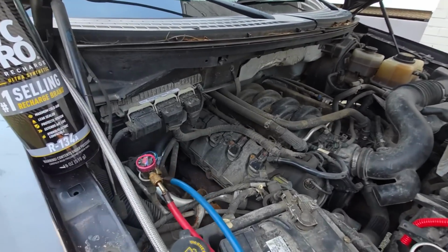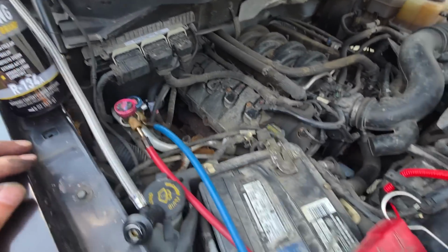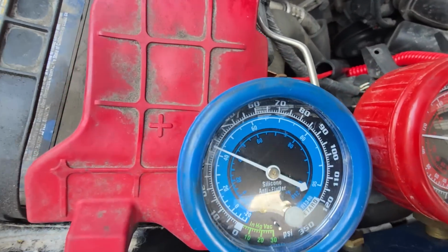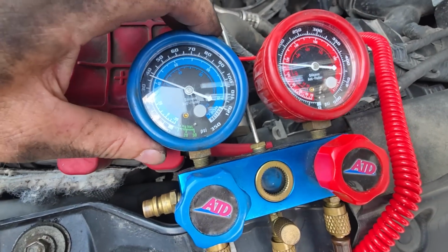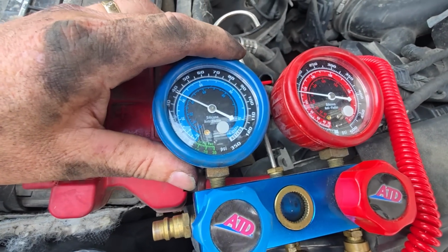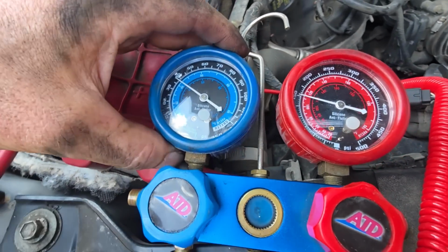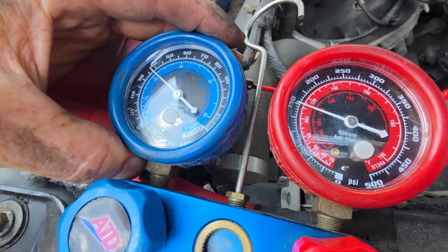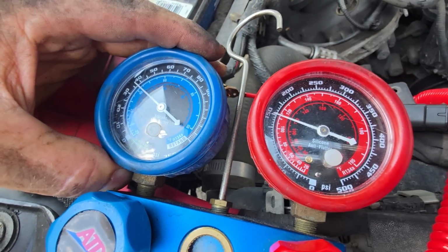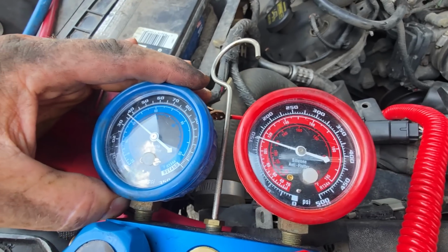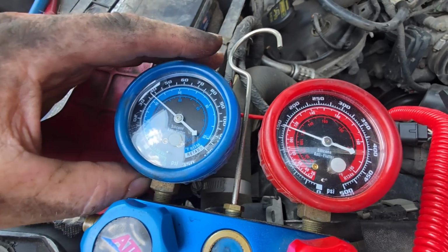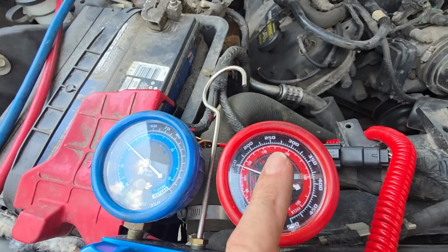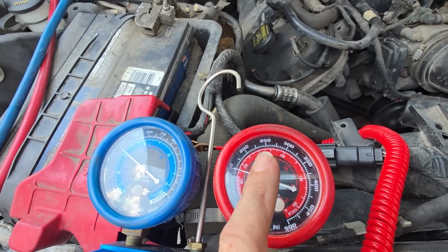I know you guys want it. I don't like to do it, because I don't know the exact charge level in this. Ideally, he's been adding, you said about 2 years ago you added to it. So that's obviously a super slow leak, but these numbers are low, especially that high side. I'm gonna have you sit in there around 1500 when I'm doing this, so I can watch these gauges and add. I really want to be probably 2, 2.25 on the high side is what I'm looking for.